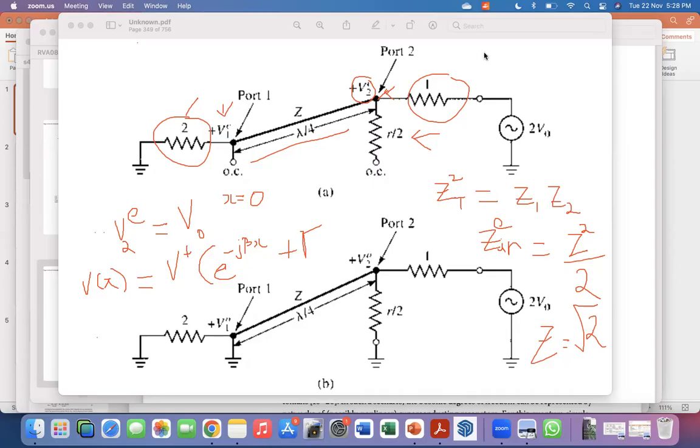Why are we doing the calculation of this segment? The calculation is easier to do this way. And then you use the fact that it's a symmetric network. So this way and that way will give you the same result. In the end, this is not the full calculation, right? I have only done now even mode excitation for one side.